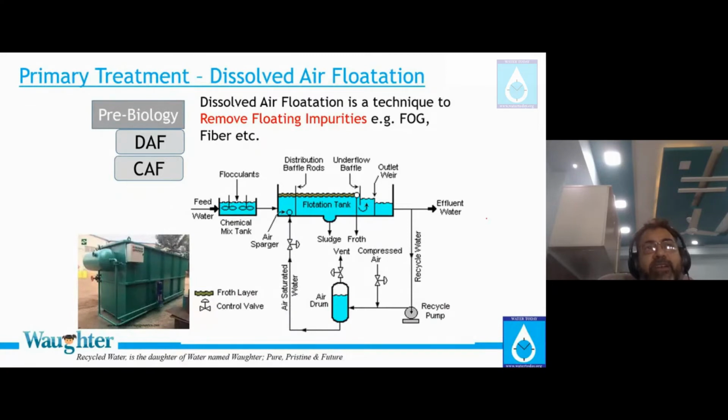So I'll suggest that gentleman, okay, what you do, one thing, you take a DAF and then you go for electrocoagulation and just filter the effluent through ultrafiltration and please put it into the garden. The gentleman will ask me, sir, what will happen to the BOD, COD? I'll say, no problems. BOD under 30, COD under 100. No biology required.